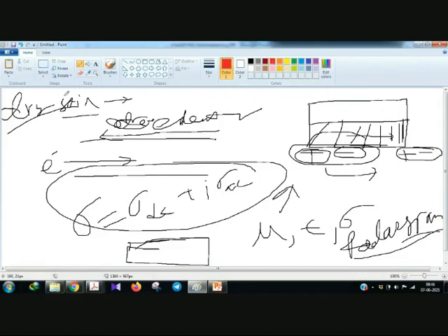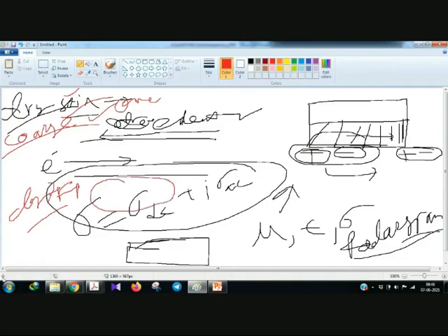Now for the dry condition, it will work fine. If the overburden is dry, then it will work fine, and if the overburden is coarse, then it can work fine. But if the overburden is clay material, a fine grain material, then the GPR signal will be attenuated more in that fine grain clay. Because clay has a conductivity of around 100, which is a huge conductivity, and sand has a conductivity in the order of 1 Siemens per meter. So sand is far more resistive than the clay material.